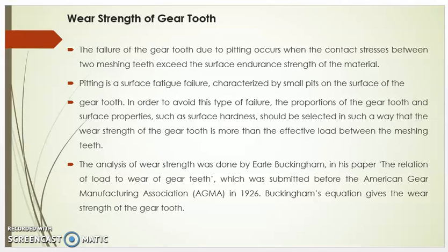In order to avoid this type of failure, the proportions of the gear tooth and surface properties such as surface hardness should be selected in such a way that the wear strength of the gear tooth is more than the effective load between the meshing teeth.